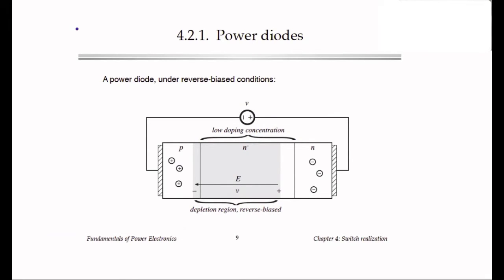When designing power diodes, there are various trade-offs. One is the trade-off between the blocking voltage or breakdown voltage of the diode versus the forward voltage drop versus the switching speed. This is a trade-off that is inherent in any of our power semiconductor devices. But it's interesting to see how it works in the PN junction type diode.